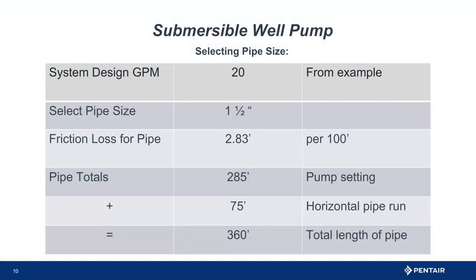Starting from the top, how many gallons does the home require? Now yes, the primary limiter is the well. If the well only produces 12 gallons per minute, that is the limit. For class, it is always assumed that the well production can meet the need. So, a traditional method of determining the system demand is to count the points of water usage and total them up. Then multiply this number by 1 gallon per fixture. Doing this, we determine the system needs 20 gallons per minute.